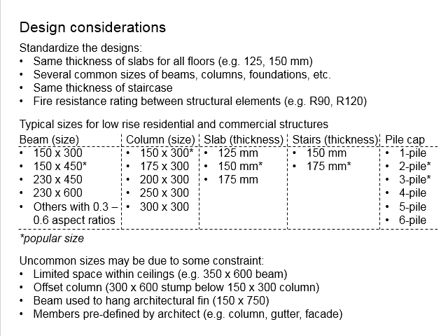Next, you will need to use some common sizes of the beams, columns, and foundations. And those sizes, if possible, should be something which is commonly seen in the construction industry. Because if you are talking about the standard size mostly applied in the construction industry, it is very easy for them to remember and monitor, and with sufficient experience, just by looking at the members, they will know more or less the size is accurate.